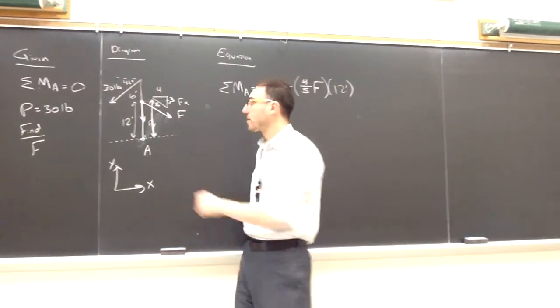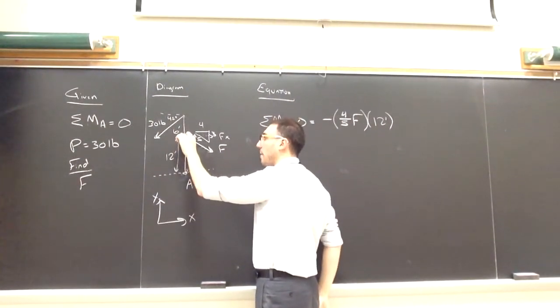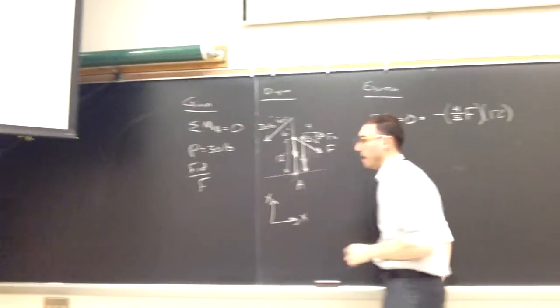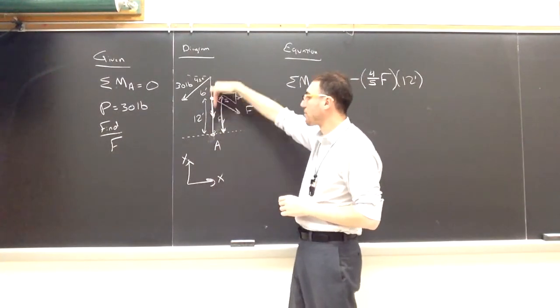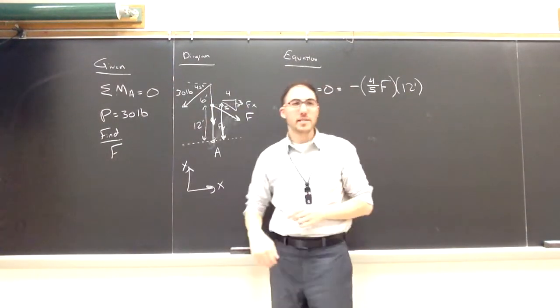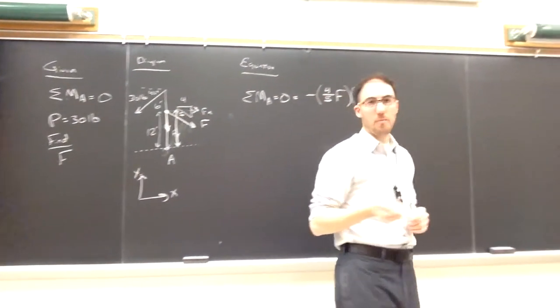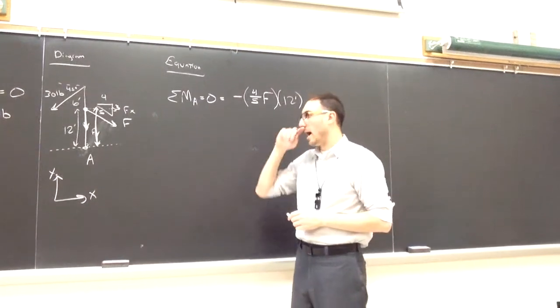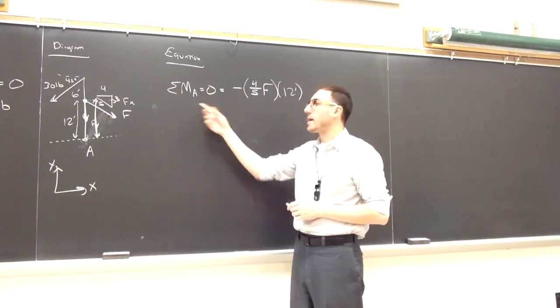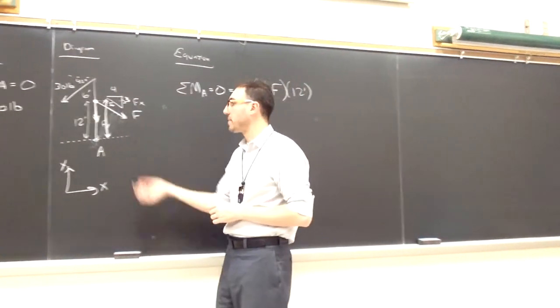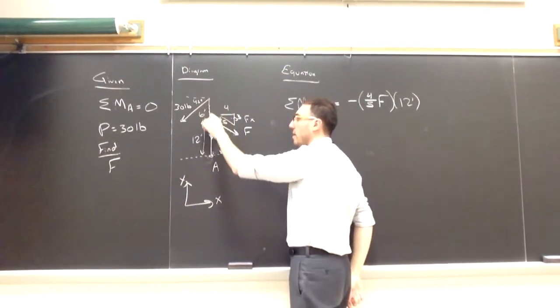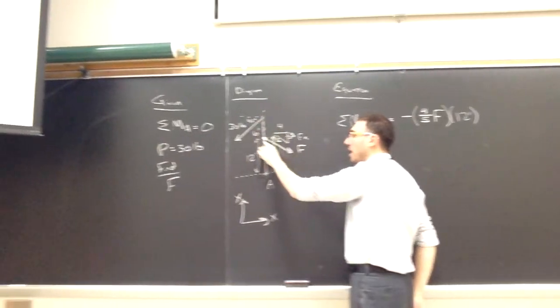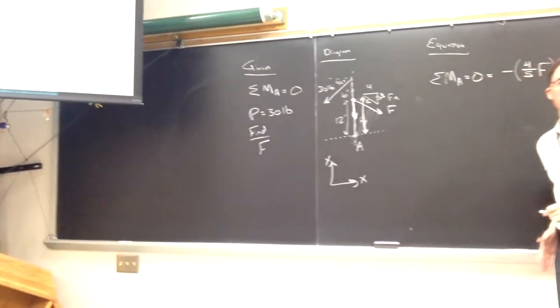That will be 0, because if we draw how much is parallel in the y direction, that will have its line of action passing through A. So the rule is if the line of action passes through our point of interest A, the point we want to know the moment about, it will have no contribution to the moment because its perpendicular distance is 0. The force is on the same line that goes through A.